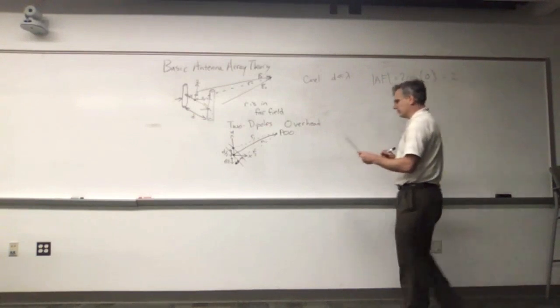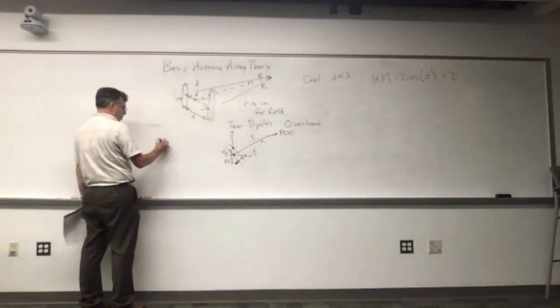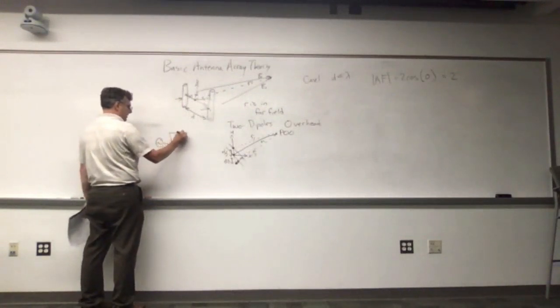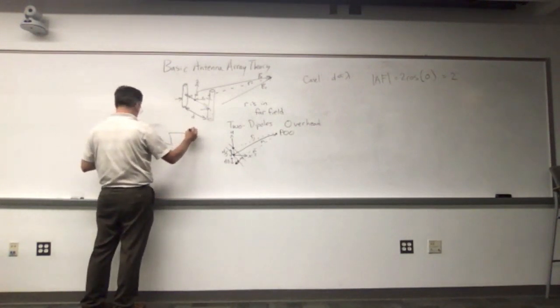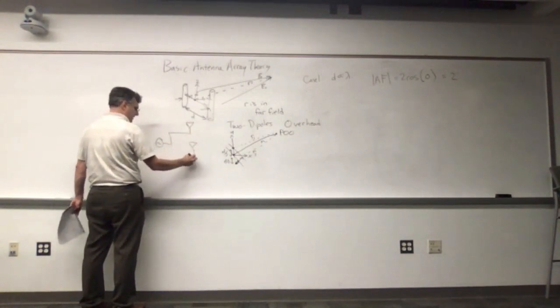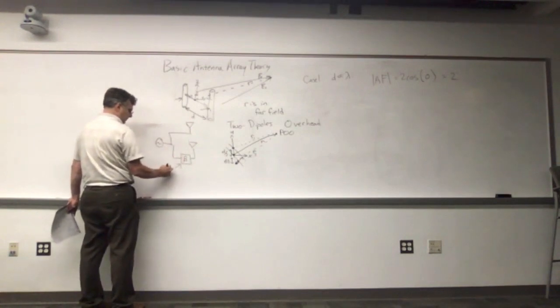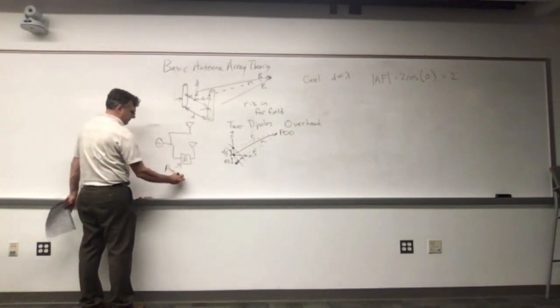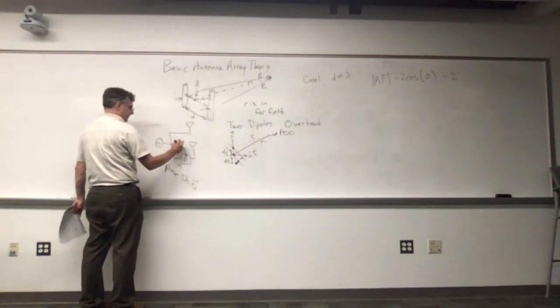I want to put a little bit of generalization here, too. I'm going to take the source, and I'm going to add one more degree of freedom. I'm going to flip the source up. I'm going to drive these two elements. These are the standard bent hanger symbol for antennas. But then I'm also going to allow something called a phase shifter. Some device that introduces an arbitrary amount of phase shift, beta, and